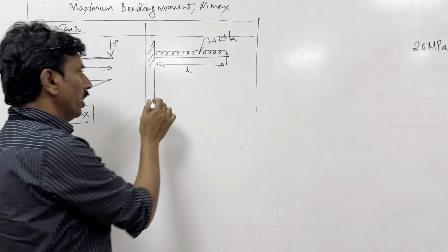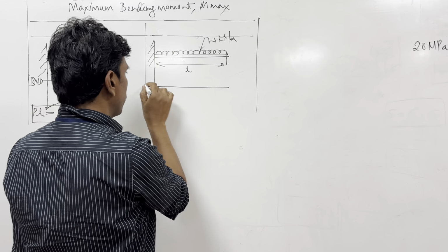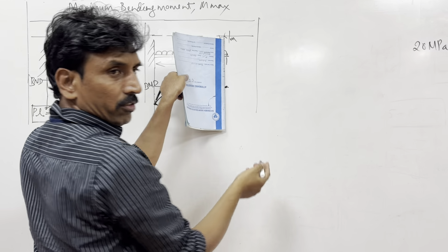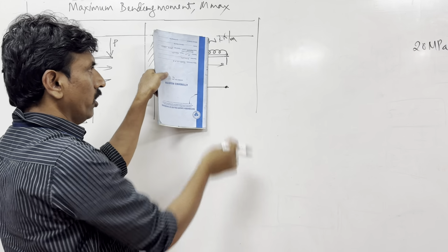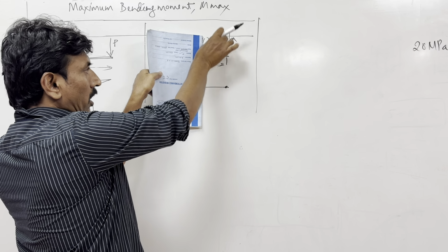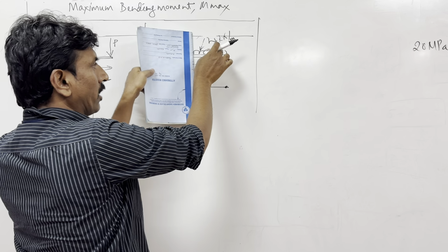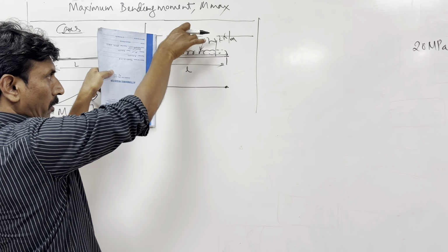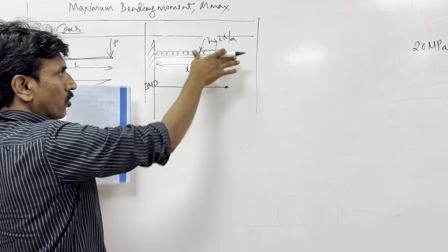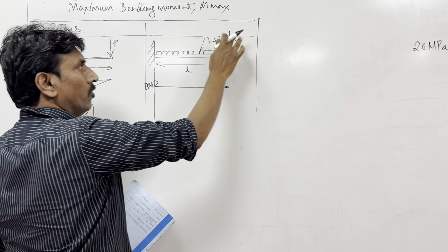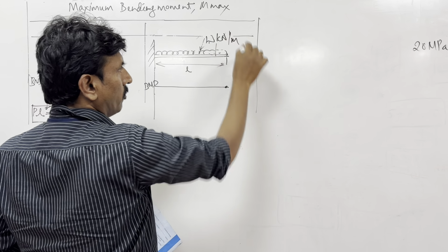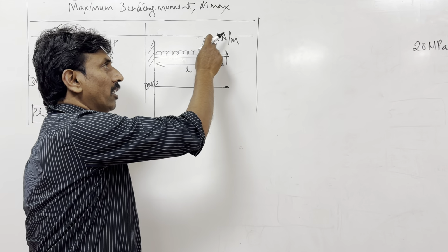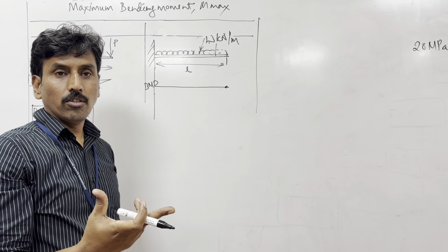Okay. So here, if I have to draw the bending moment diagram for this, this is the bending moment diagram. So here, how much is the bending moment? 0. As you go further, the whole UDL can be placed at the center at some distance, the whole UDL exactly placed at the center into half distance here. So if this is W kilonewton per meter, what is the total UDL for L meters? For every meter it is W. For L meters it is W into L.